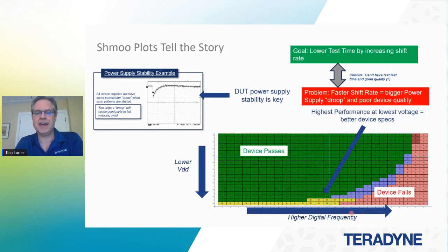And so you can expect that as the VDD goes down and the test frequency goes up, you'll eventually get failures and you'll get passes in the opposite condition. And then there's sort of this area in the middle where sometimes it'll pass, sometimes it'll fail. So it tends to be a little unstable. And what we really want to do is the lower we can, the farther out we can get this sort of failing region, farther we can get it down into the right, the better.